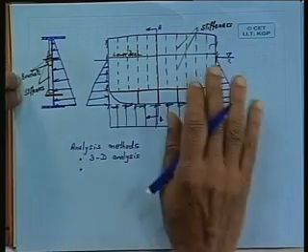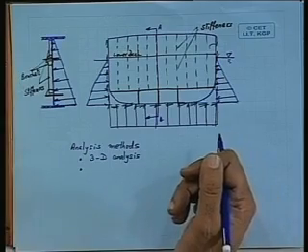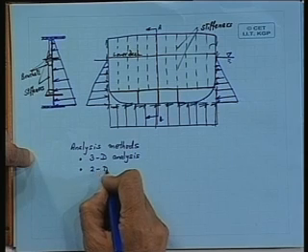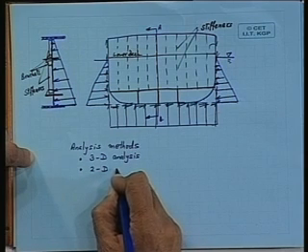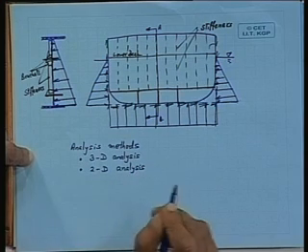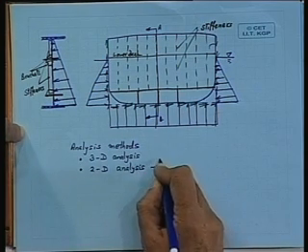But then the basic plate is 2-dimensional and the beams can be considered embedded in the plate. We can reduce the 3 dimensions to 2 and consider it to be a 2D problem. Usually the detailed analysis is done on the basis of 2D method.